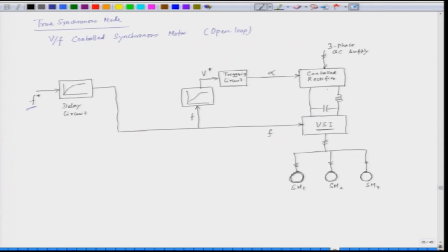We have the VDC here, that is the supply voltage, and there is a filter here which filters the VDC value, and then this feeds the voltage source inverter, and the output is AC. So, the output in this case is AC. Now, when we want to change the speed, what we do here is we change the frequency. So, this is the frequency command, the frequency reference.